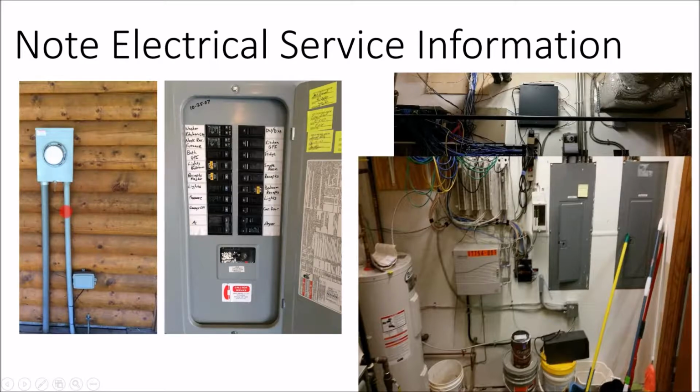So now we're going into the home, and if we wanted to do a line side connection, this would be intercepting the conductor run between the meter box and the building main. So our line side connection could go right here, and there's ample room on this wall to mount it. And so we might actually do a supply side connection here, and then go up this wall into a soffit for our internal wire run. And so what I want to do is take note of the size of this conduit so that I can get my fittings and put a box there.